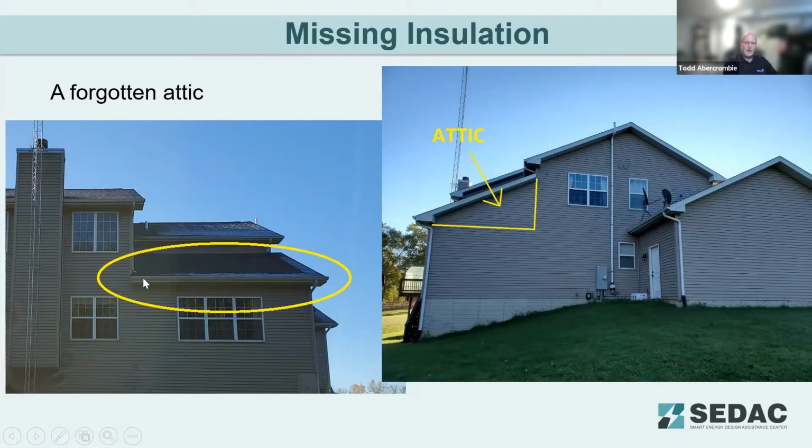But on this lower roof, which happens to be above the ceiling of that room, there's almost no frost at all, which is telling me that this is probably an attic that's not insulated at all, and that heat from the master bedroom was just going right through the ceiling, right into the attic, and warming that roof deck to a point that it didn't have frost on it. You only have frost at the edges where it was overhanging the outdoors. So just looking at those two adjacent roof lines quickly tells me this is a problem area.